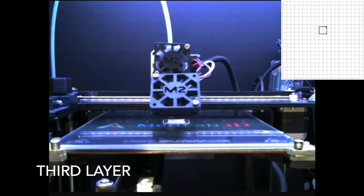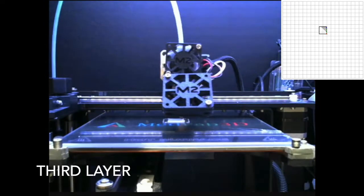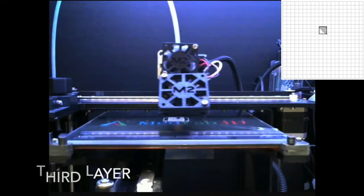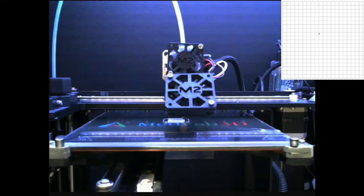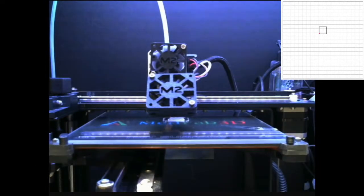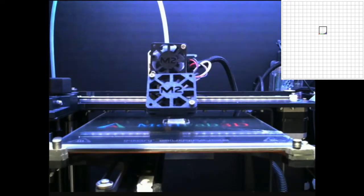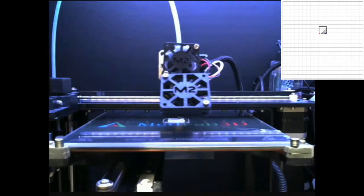The printer has completed the third layer of the part and has moved up to the fourth layer now. You'll notice that as the printer is printing, the layer is printing quicker than the layers before it. This is due to 2 reasons. One is that we print the initial layers on the part slower in the beginning to allow for better adhesion to the bed, to make sure that we have a good foundation for the part.